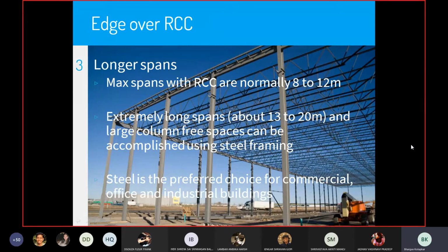But you don't have that scope for innovation in reinforced concrete. There's only a rectangle that you can use, nothing more. You can pre-stress it, but that's a different ball game. If you compare only structural steel with structural concrete, you have a lot of space for innovation, for trying out different systems, and thereby for spanning longer. That does not happen with RCC.